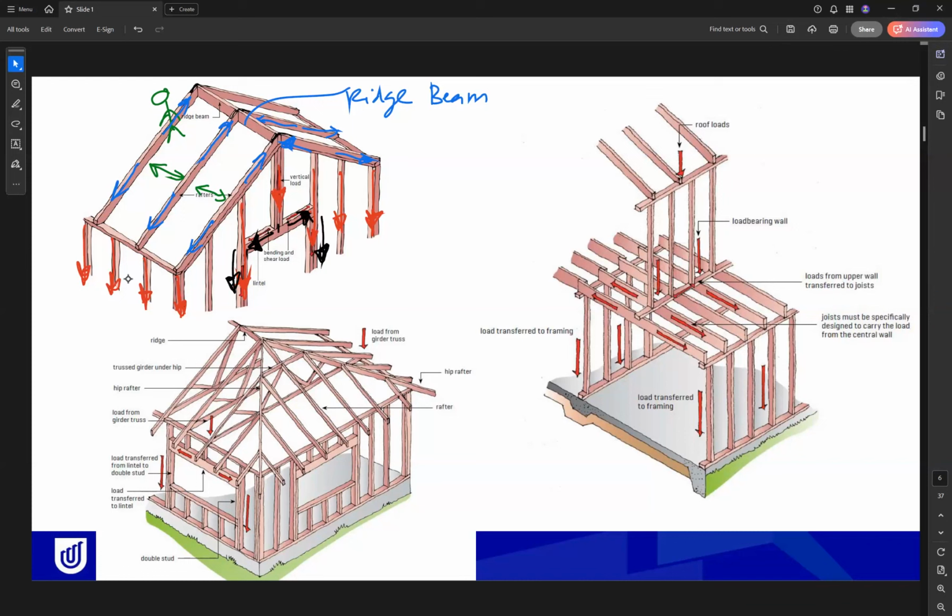Okay, so this is an example of a residential building. Here as well, same. So we have the load on the slab or the sheeting to the beam. Then the beam will transfer the load to this beam here. This beam will transfer the load to these columns here. And this column will transfer to this beam. This beam will transfer to those beams here and those beams here in this direction until reaching this beam.